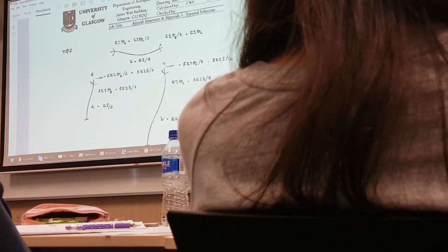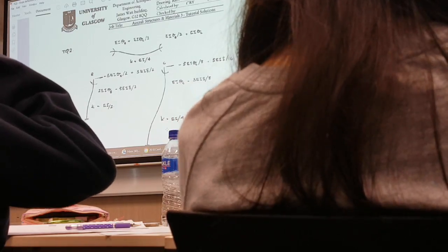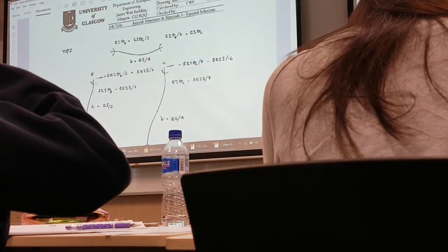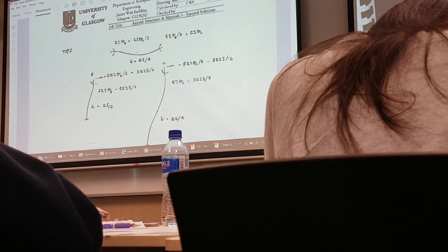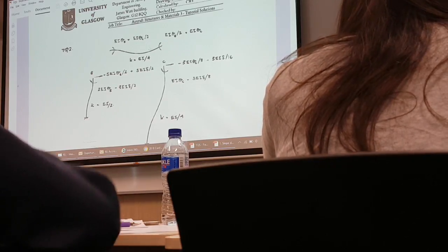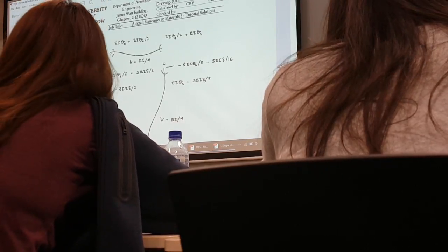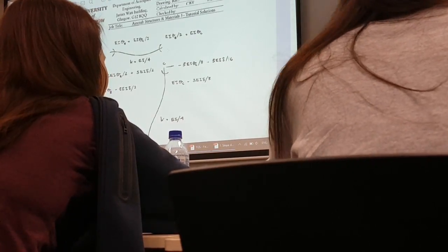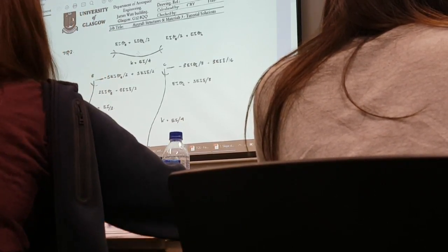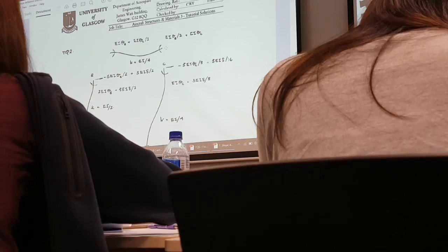Right. So after that, of course, for member AB and CD, you have to rotate the convention. But when you come to member BC, because BC is basically horizontal, you don't have to rotate at all. So if you apply the member equation straight away, this is node 1 and this is node 2. And there is no force in member BC because this member did not move downwards. It's only the entire structure, of course, that would move laterally, I mean, from left to the right.